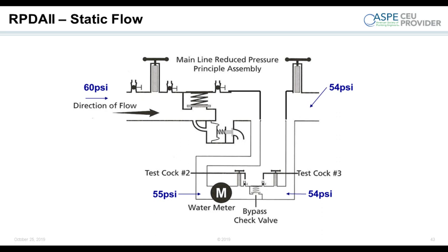The reason for that is essentially that we want to make sure that if both checks are fouled and water gets past that second check, the first thing that it hits is the bypass. Typically the bypass is on the lowest point of the valve for that reason. Once you install it vertically, it can gravity feed directly past the relief valve and past the first check, which is why RPDAs and RPZs in general can only be installed horizontally.